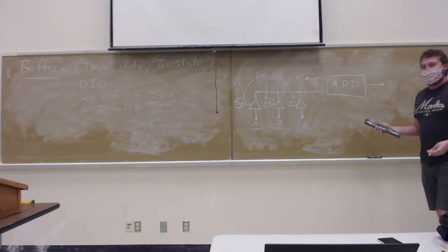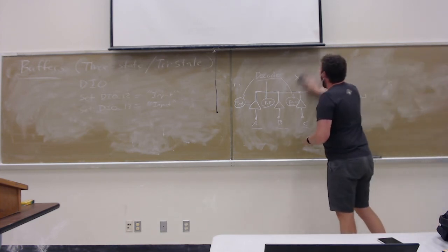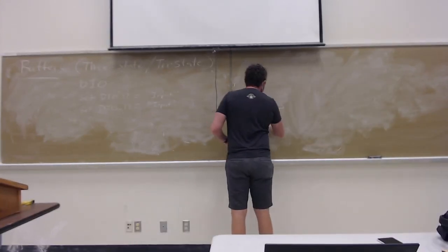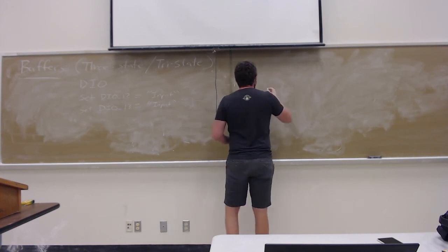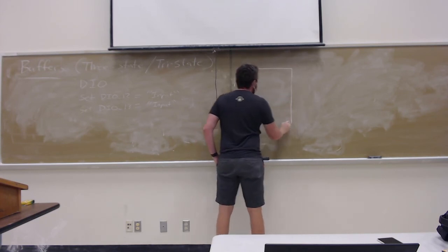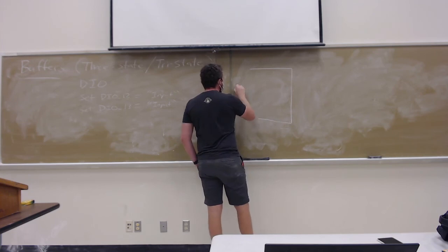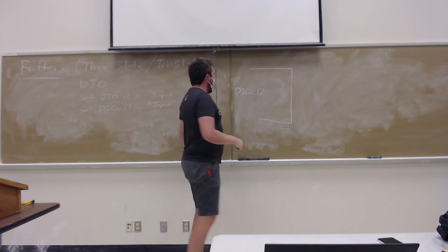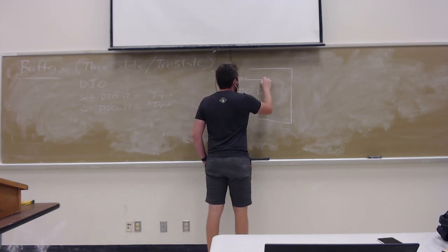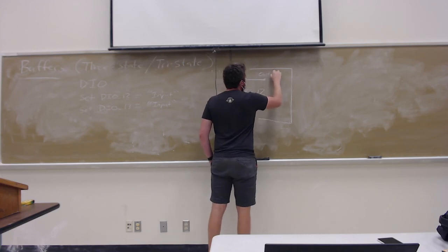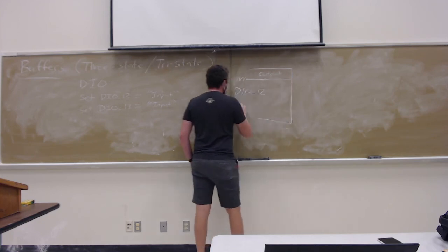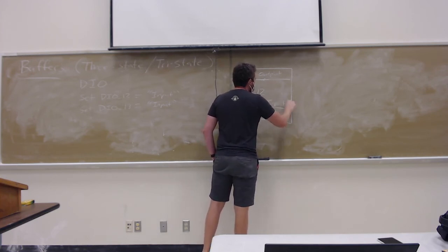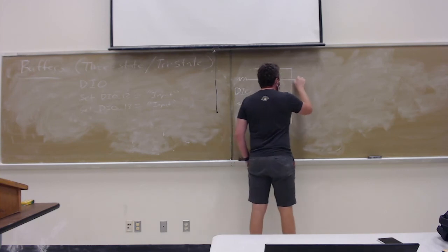It turns out, spoiler, the answer is by taking advantage of these tri-state buffers. What happens under the hood is, in a block of circuitry that is just labeled as, let's call it DIO 12, there will be an actual physical circuit that is the output, and an actual physical circuit that is the input.